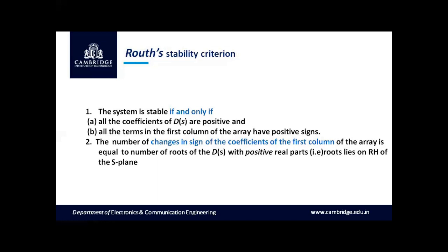As discussed already, the number of sign changes gives you the number of roots which is present in the positive real part, which is nothing but the poles which is present in the right half plane of the S-plane. Let us solve few problems related to Routh stability criterion.